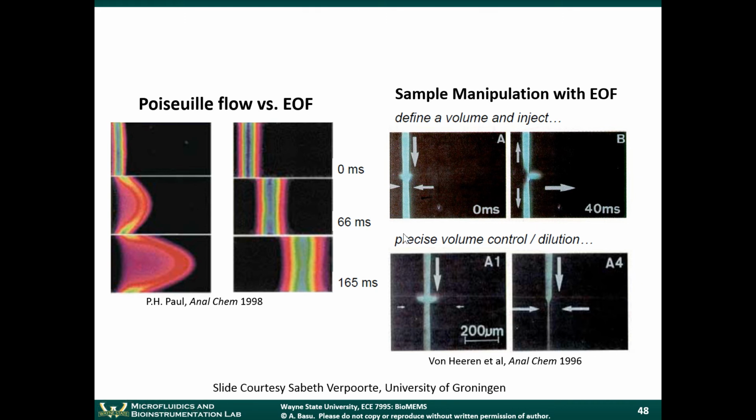Then they remove the voltage here and they apply voltage horizontally instead. When they apply the horizontal voltage, you'll notice that a little bit of the sample starts going through this channel here. And this is a technique that's used in microfluidic separations. We'll talk a little bit more about that. The point to be made here is that just by applying voltages at different parts of the chip, you can get flow in whatever direction you want. So from an instrumentation standpoint, it's very simple. You're literally just putting voltages at different places.